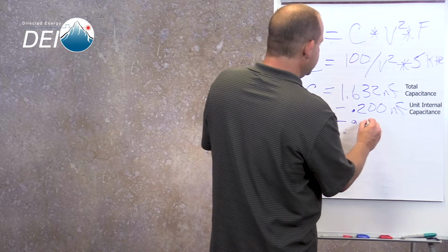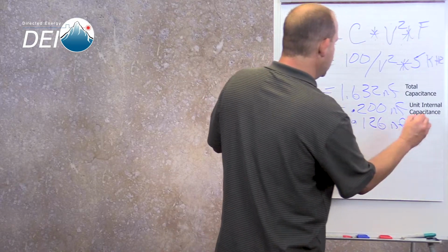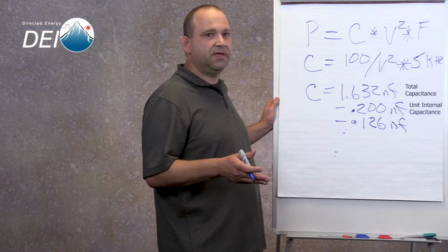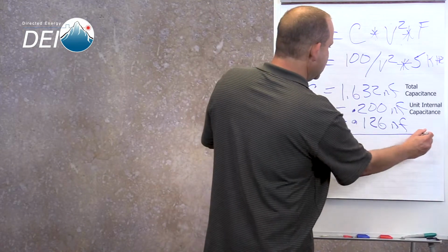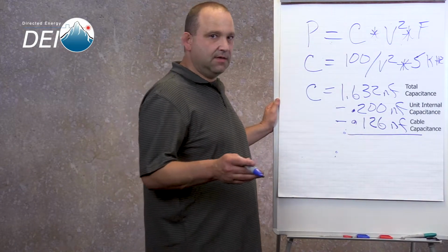Then subtract 0.126 nanofarads or 126 picofarads, and that is from the 6 feet of cable that is supplied with the unit.